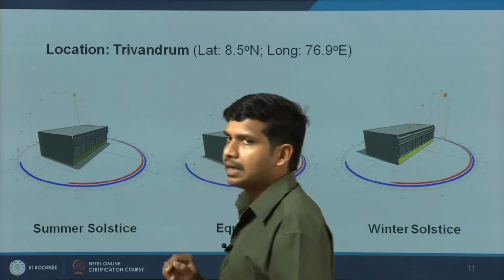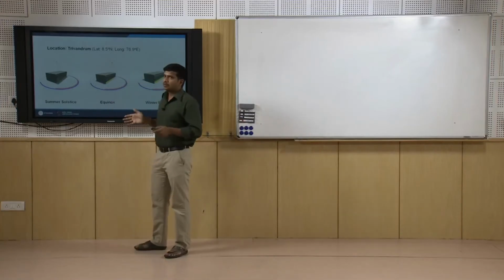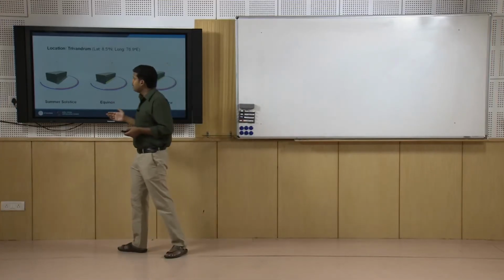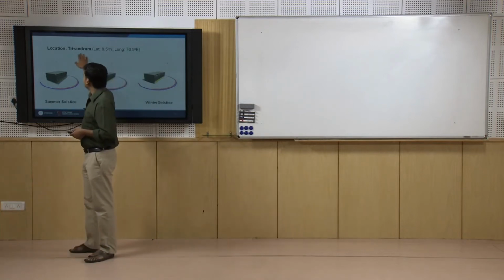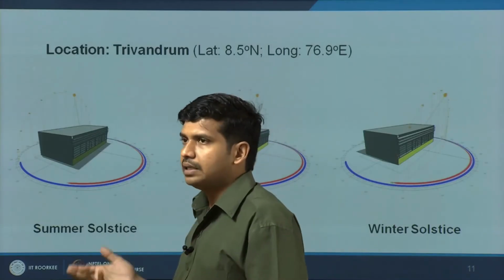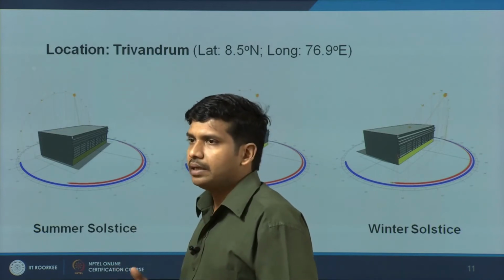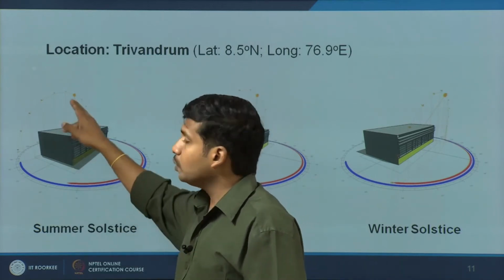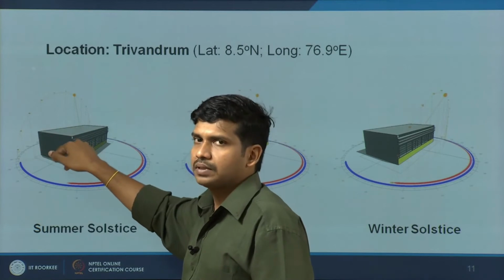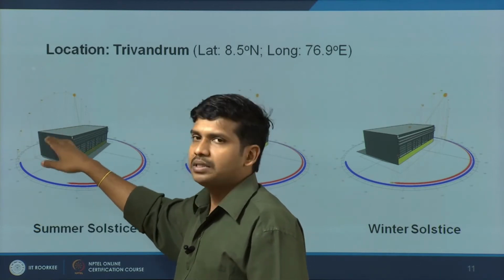What implication does this have? If you have a northern wall with large windows, typically during summer, especially in latitudes like 11, 10 or even 15, 13 degrees north, you will have solar incidence on your northern facade and northern windows during summer months.